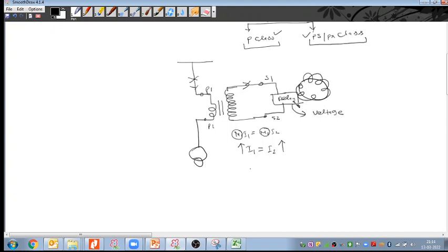At the event of the fault, when the relay operates, it gives a tripping command to the circuit breaker, and the circuit breaker clears the fault. Then the CT is protected, and the relay is also protected. So the CT requirement is governed by the relay requirement. Each manufacturer, each company, each model of relay has a different CT requirement. So based on the relay requirement, we have to decide the CT. That is the reverse calculation that we need to perform.